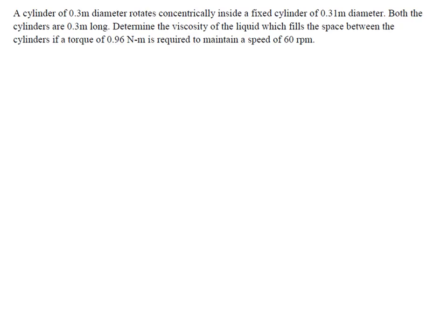You have to find the viscosity if the torque is applied. Whenever torque is given, you can find out force. Force into distance, that is F into R, will give you torque. We always know that the external torque should be equal to the internal torque. That's the concept used here.